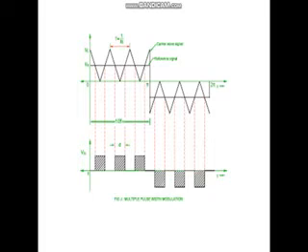As I already mentioned, the pulse width modulation technique is a comparison methodology. Here there are two signals, one is the carrier wave and the other is the reference wave. The two signals are compared, and based on this the pulses are generated. The pulse width modulation control methodology is a feedback control. That is, the output voltage of the inverter is always sensed, and if there is any variation, the width of the pulse can be varied.